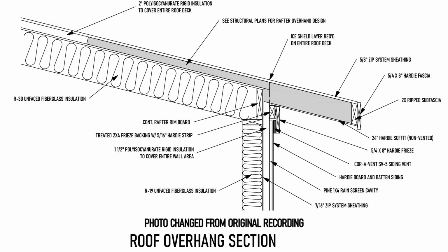In this case, it says 2 layers of 2-inch mineral wool or fiberglass. And then they didn't describe, they did fire retardant treated furring boards. So they're trying to gap the cladding on the outside of the building off of that insulation. So that's how they're going to do that in this case. But this is a wall or roof assembly. It oftentimes will describe how the eave of the building is supposed to be created, where the block goes, where the trim goes, what sizes the trims are going to be used in this particular case, where all this stuff trims out. There's a lot of important information that can describe different complexities here in a wall and roof assembly.